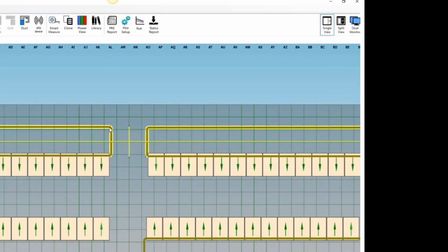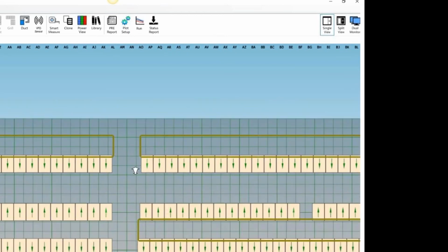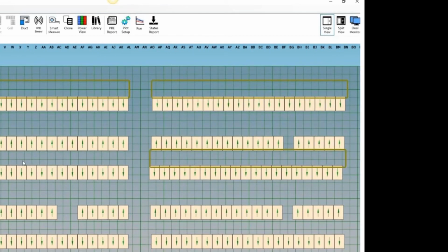Now I do want to align them. So I hold my cursor, I light them both up, hold my cursor and say align to, in this case, Z-min. Hold your cursor over the one you want to stand still. So here I'm going to Control-V because I've already got it in my paste buffer. And I kind of drag it into position. I don't really worry too much about its exact position because I'm going to line it up later.